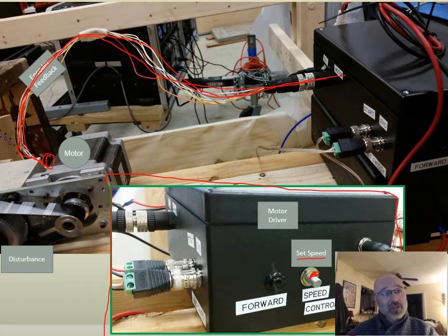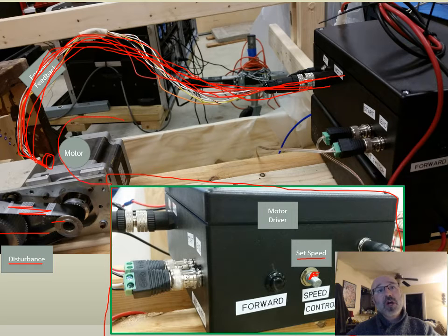So we can see down here our disturbances might be something like the tension in this belt, the alignment of these gears and pulleys, or, if we keep going over to the side that we can't see, something that's changing, putting a slight tweak on the load of the antennas, which is increasing the friction and the alignment on the rail system that's guiding this and making it not so smooth a motion. The friction increases, so we need to bump up the amount of current going to our motor to make up the difference because it's slowing it down. So we have that constant feedback from the encoder going back and forth between our electronics box and our microcontroller, letting us know how to adjust to maintain that constant speed.